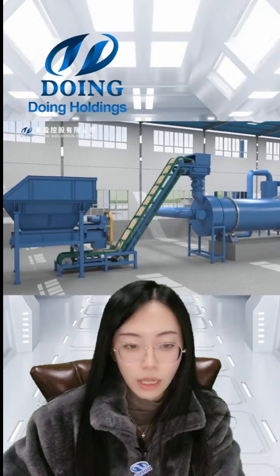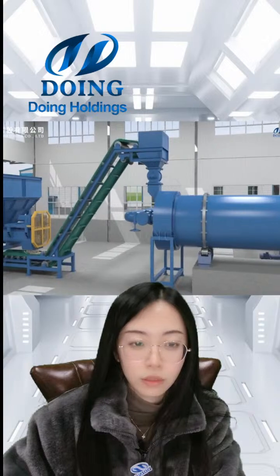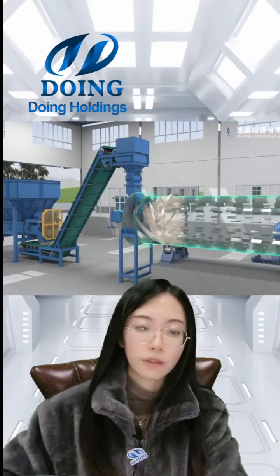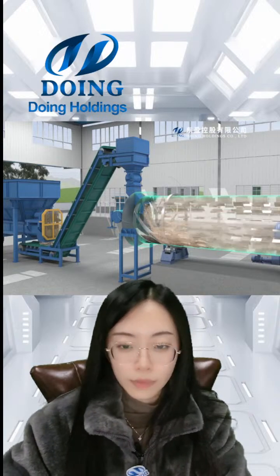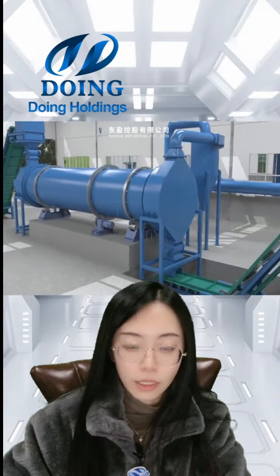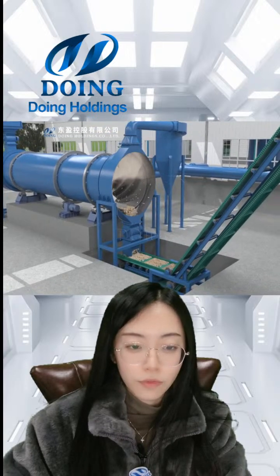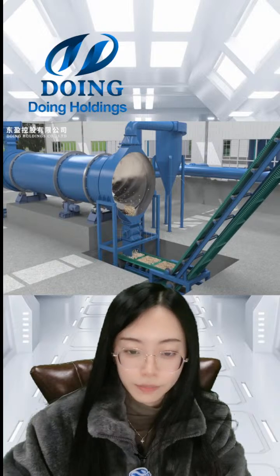We can get nearly 30 to 40% charcoal, 20% wood vinegar, 30% tail gas, and 6% tar. The calorific value of the gas is nearly 1,100 kcal, and the calorific value of the tar is 5,000.